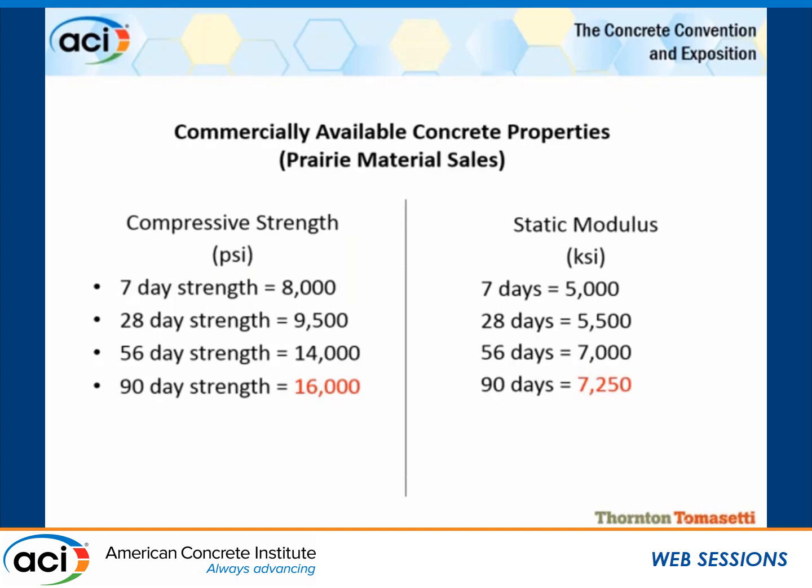And we talked about even higher strength moduluses, what it would take to get to 7,000 KSI modulus back then. And the thought is you'd be specifying strengths probably around 16,000, maybe even higher. And at that point, the talk was that you may have to import aggregate from Wisconsin. The trap rock aggregate up there is much stiffer. The coarse aggregate is a very key driver for the eventual modulus on these projects. So again, these were setting the ground rules for what could be achieved commercially on these projects.